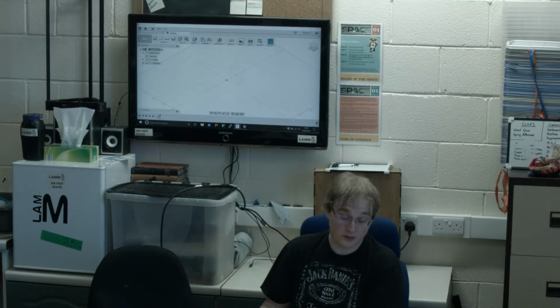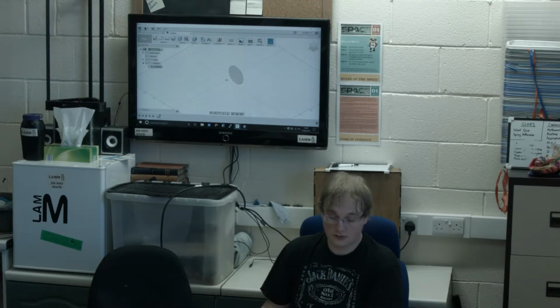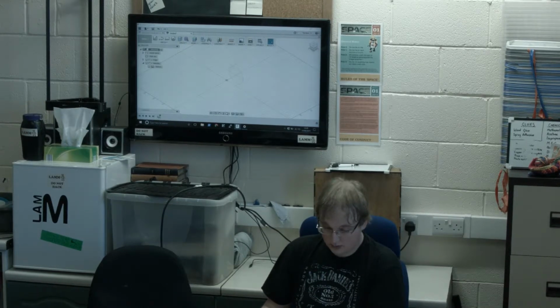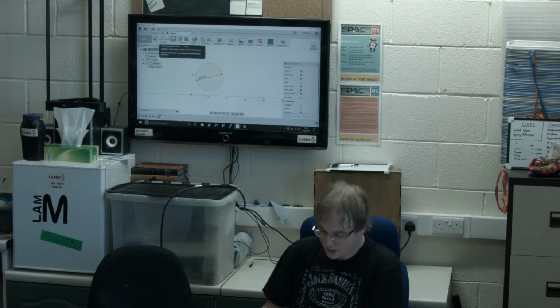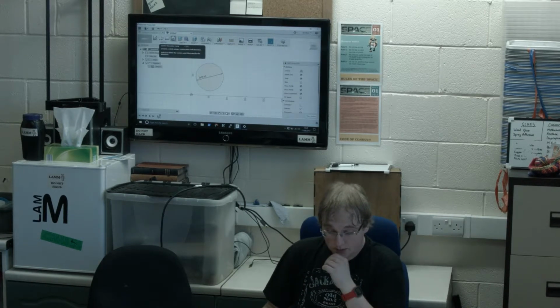If you need to get back into your sketch, which we do now, there's the option bit on the left hand side that gives you access to all the different bits, like all your planes, your origin and extra views. You can customize extra views. But you see Sketch 1, which highlights the circle. If you double click that, it'll put you back in it. There. So we'll need a second circle for this.